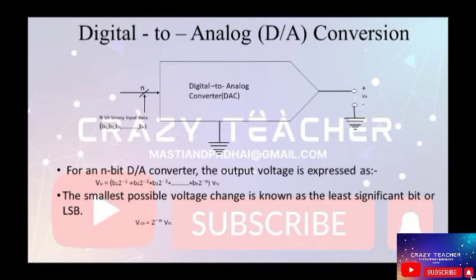It is just slightly less than this VFS, so that way you will get a value which is very close to VFS. So you can say that this is the voltage level that you are getting, so that you are getting the full scale range. So that way, these digital to analog converters are useful for converting the digital value that we have got after processing into some analog signal to be sent to the environment.